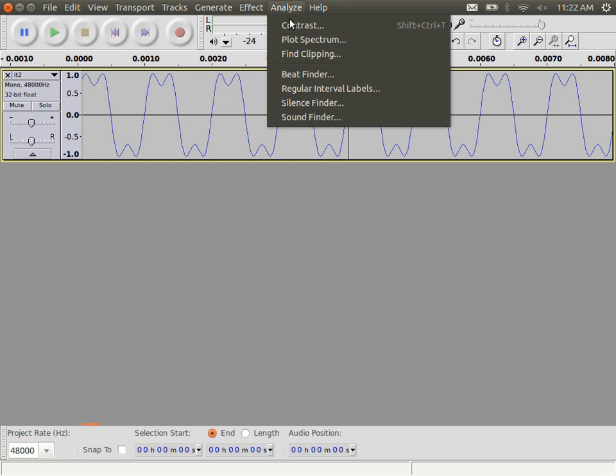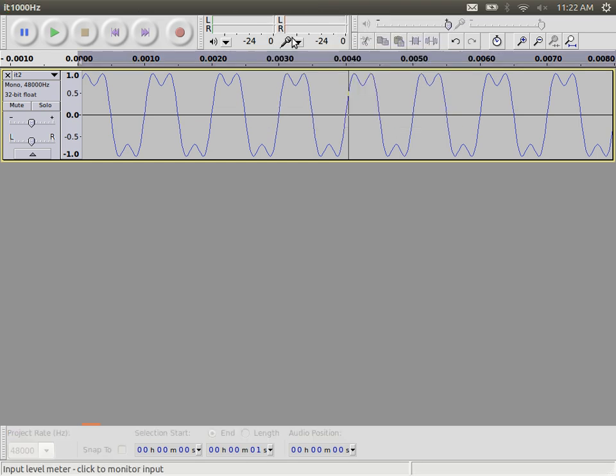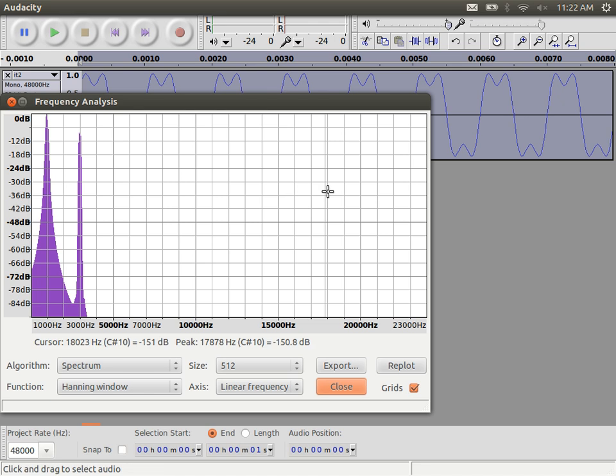So currently we have the plot in the time domain. Here's the plot in the frequency domain. Now, because it applies some algorithm to calculate this, it's not always 100% accurate, but we see the two peaks. At 1000 hertz, there's a peak, and at 3000 hertz, there's a peak. The two components. And, okay, we have some peak amplitude, and the second component has a lower peak amplitude. It should be 1/3. So that this should be 1/3 of this one.